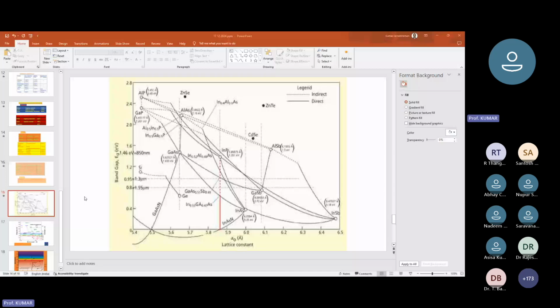There is a standard in terms of these solar cell efficiencies by NREL. This is an internationally recognized agency in Colorado in the US. And so you can see, for example, the purple color is called 3-5 multi-junction solar cells. As I said, it is a tandem solar cell. So this is close to 50% efficiency, which is used in space applications. Whereas if you see the terrestrial applications, which is around 20% efficiency, silicon, for example, this blue color, this is